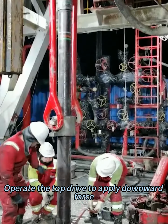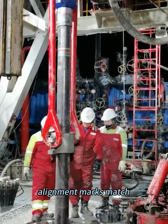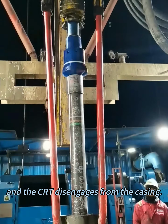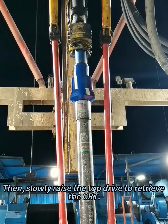Operate the top drive to apply downward force, then rotate counterclockwise until the device locks, alignment marks match, and the CRT disengages from the casing. Then, slowly raise the top drive to retrieve the CRT.